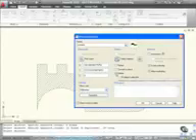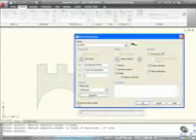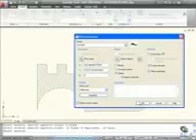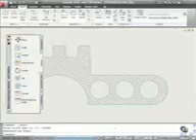I'm going to use the delete setting again here, like I did previously, and also scale uniformly and allow exploding. I'm also going to go to my block unit, millimeters here, insert a hyperlink if I need to, and I am going to open it in the block editor because I'm going to edit the block. When I OK that, the block editor opens.